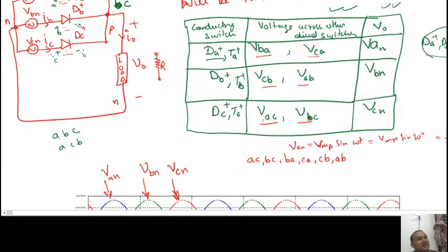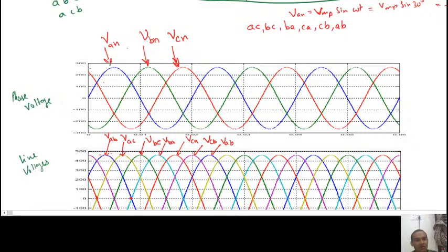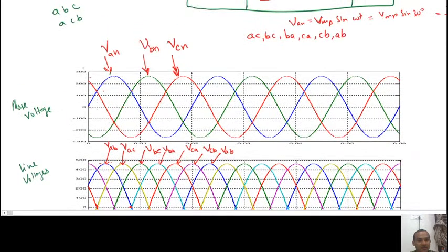As soon as C gets turned on, even if A is positive, because C is more positive, the more positive voltage will be applied across the negative terminal of A, hence A will become reverse biased. I am drawing A's positive voltage here, at the plus terminal, and this is the minus terminal. Here A is already applying, and now C is applied. Although A is also positive, C is more positive. So ultimately this diode will become reverse biased.